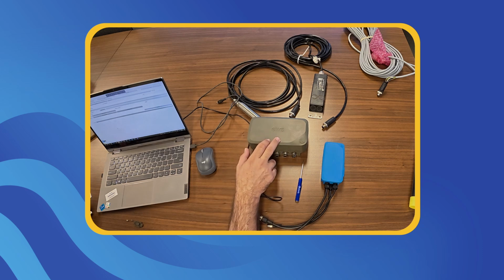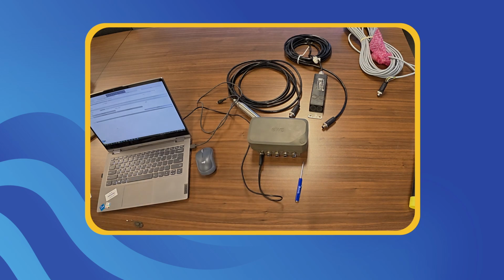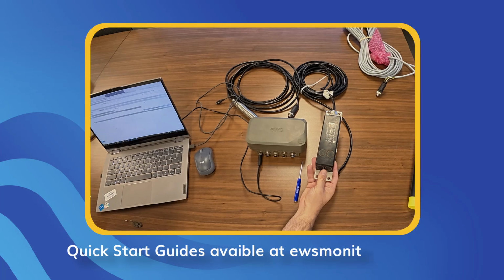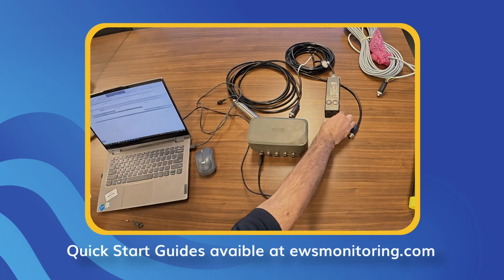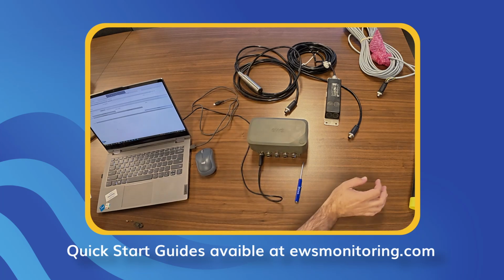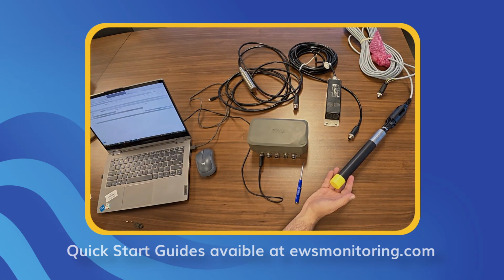may be required. For this setup, I'll be using an EWS EMT device, but it will also work on the regular Switch. You may just need some M12 splitter cables or connectors and to reference the EWS Quick Start guides on our website, ewsmonitoring.com. Today I'm going to connect to a Modbus 485 Doppler velocity meter and vented level sensor. Also an SDI12 turbidity sensor.